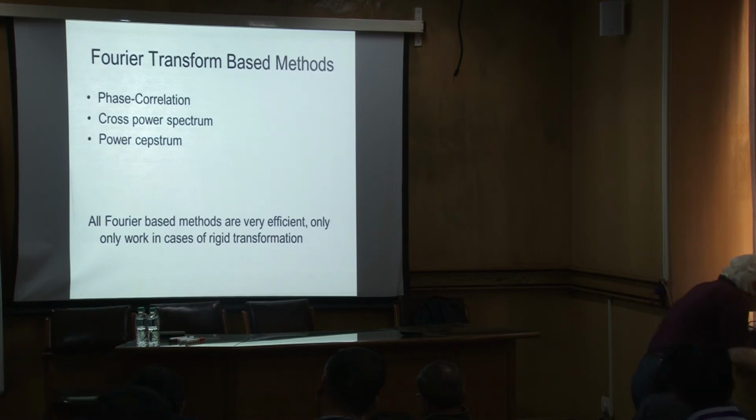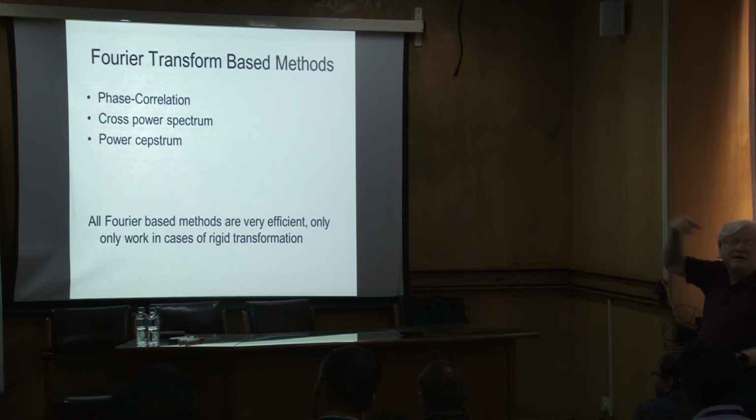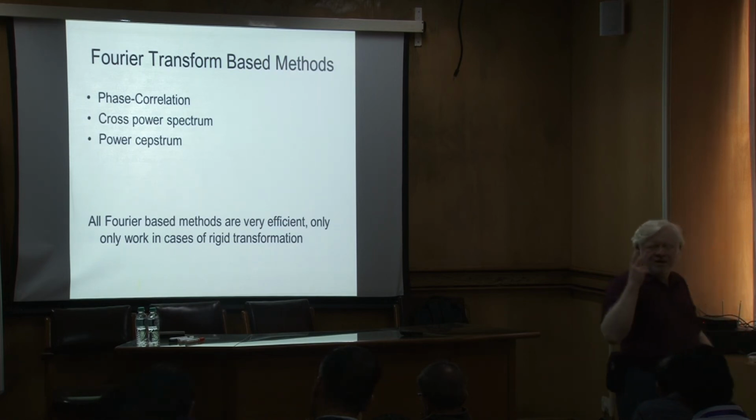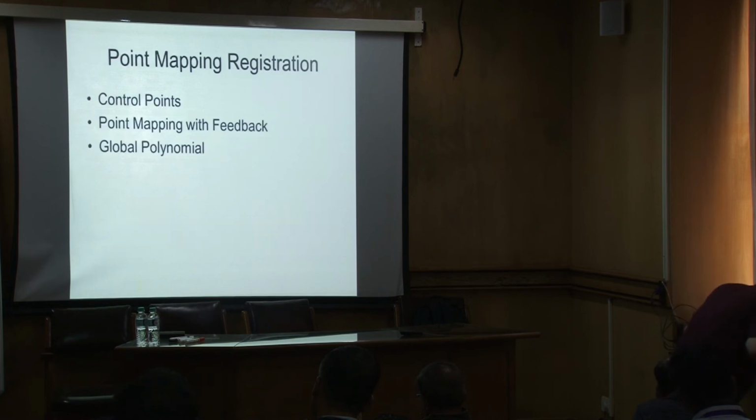So, you could use these various techniques to find it, and the Cepstrum is another very interesting approach, where you do not take the spectrum as it is, but you take the logarithm of the spectrum, because the magnitude spectrum is always non-negative. So, you can plot the magnitude spectrum and you can use that for doing it. This Cepstrum is a very interesting creature, and if I find time I will tell you how very interesting things you can do with it.